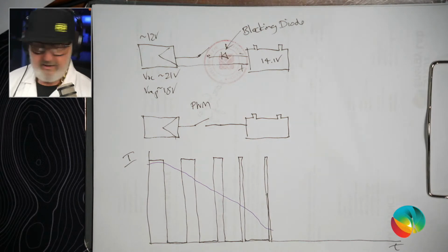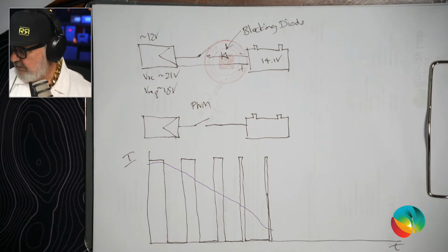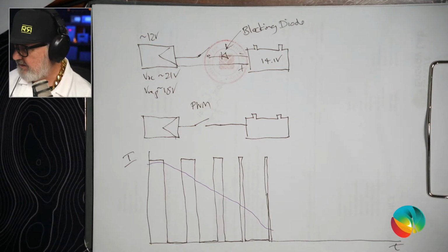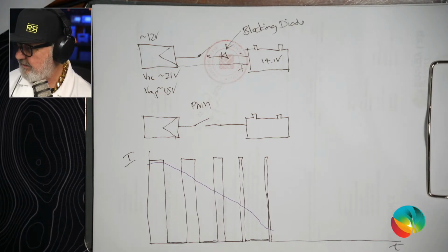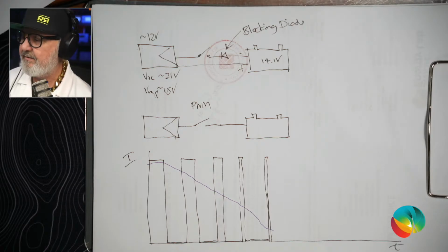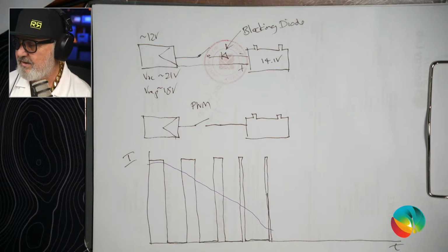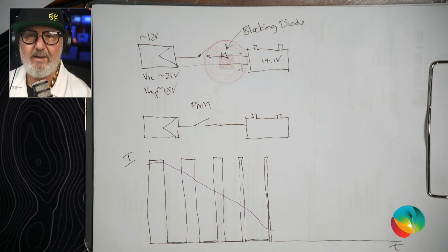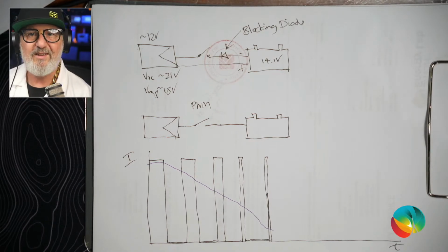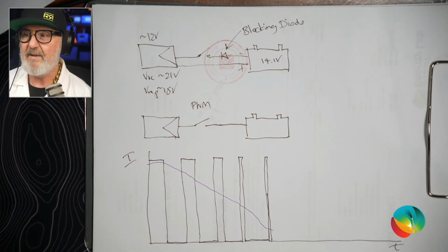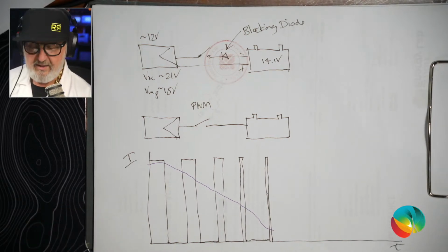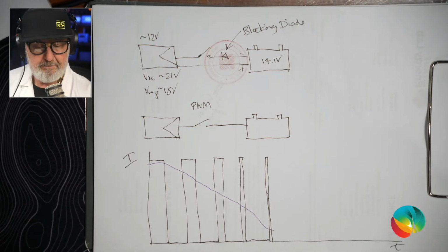Okay, so what are we looking at here in the question land? Just checking. Yakiti says, I'm looking to use it to trigger a shunt trip breaker for a 24-volt DC supply, so when EarthGuard triggers it, it can shut down the main DC isolator. Oh, very clever. Okay, so you're basically turning a detection into an interruption. So even though the standard actually requires fault detection, interruption would be a nice thing as well. So very, very clever.